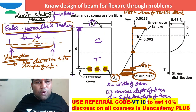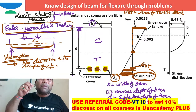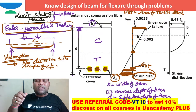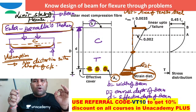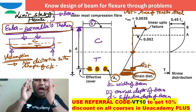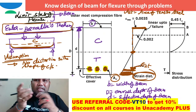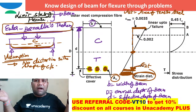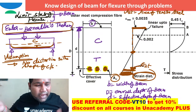Some people are saying, "Sir, you are using this Bernoulli's theorem." This Bernoulli's theorem is valid even for composite members also, and it is valid up to failure. When it is valid up to failure, it can also be applied even for the limit state of collapse. Just before the limit state of collapse the structure is not going to fail. If the structure is completely failing, I can say the structure has attained the limit state of collapse.